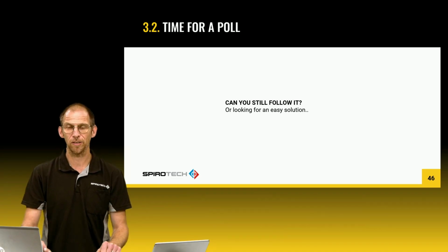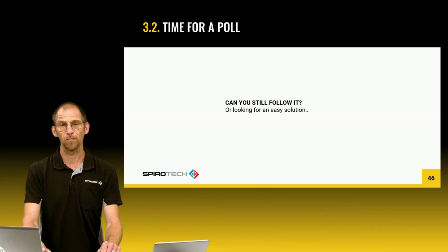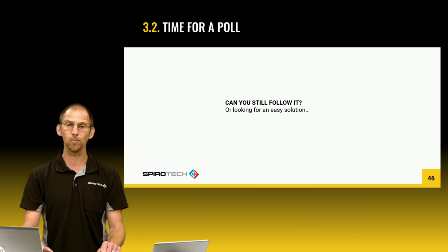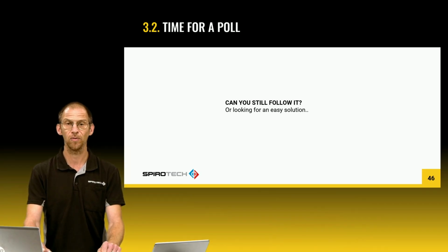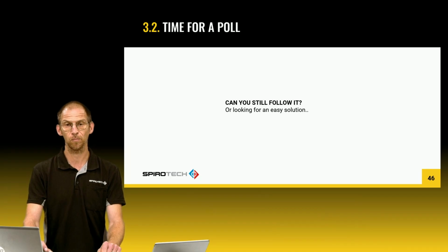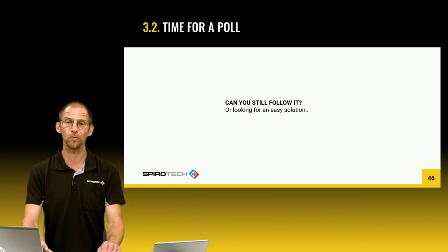Now, while you're answering, a short recap. We've mapped out what you need for a correct selection, so pressures, volumes, including the expansion volume, and temperatures. We also touched briefly on fixed gas versus pumped spill type systems. With pumped, the tank is essentially pressureless, so you can use almost the full tank volume, which often means a smaller vessel and therefore less required floor space.